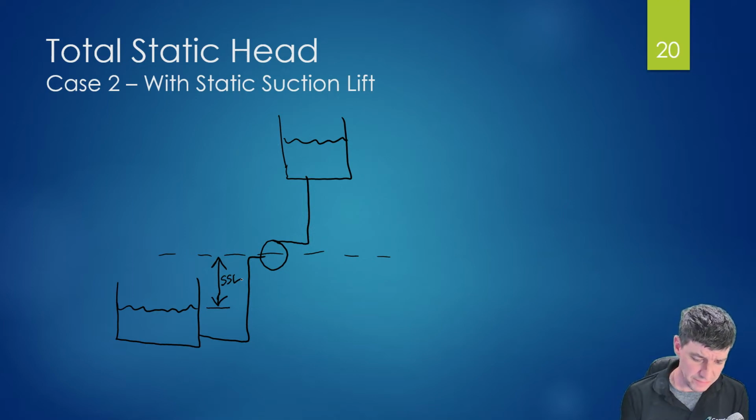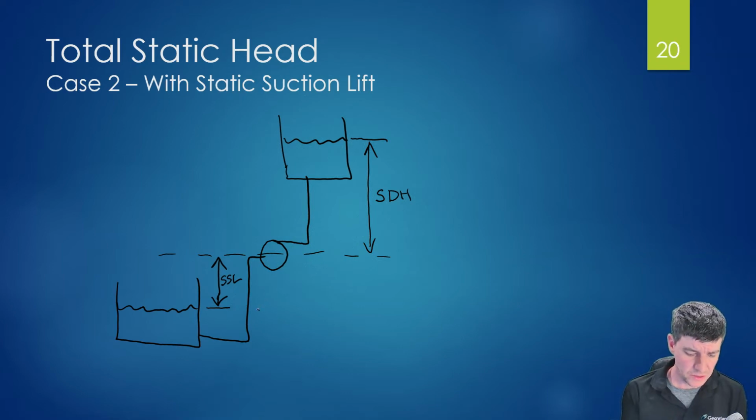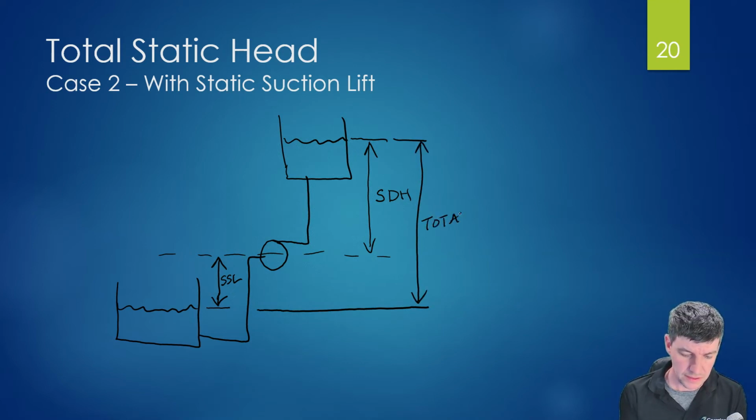The measurement from my upper reservoir height down to my center line of my pump was my static discharge height. And the total height, so my total static head, would be the difference between the two water levels, and that would be my total static head.